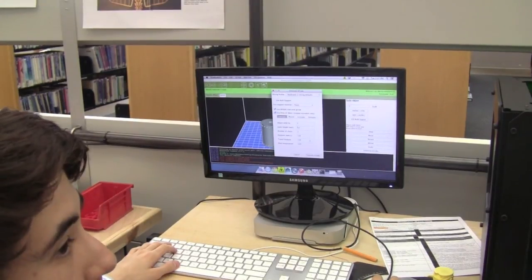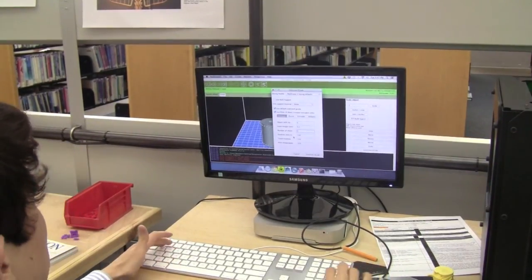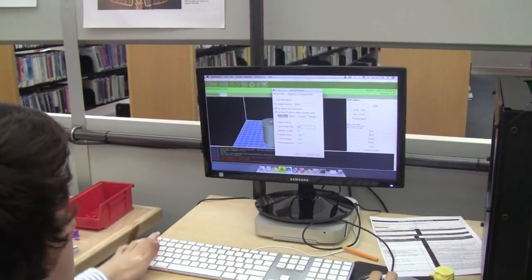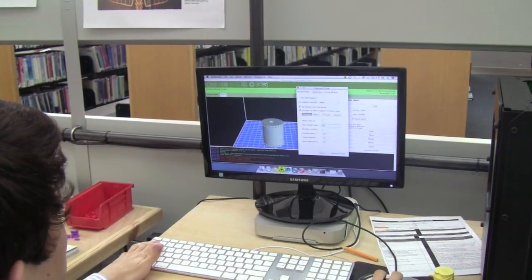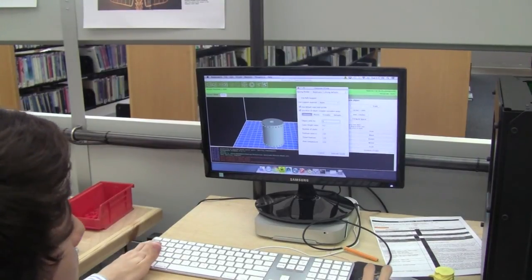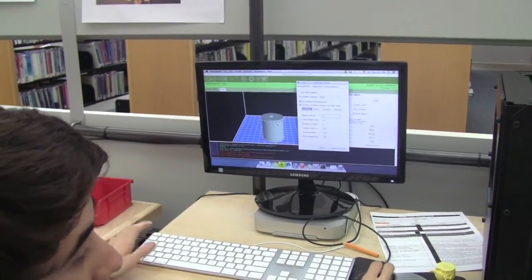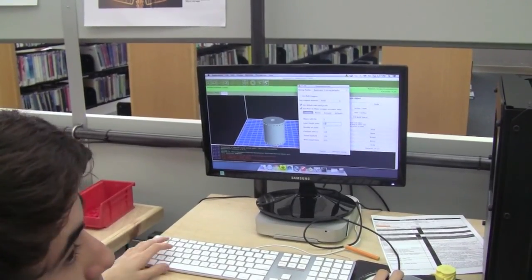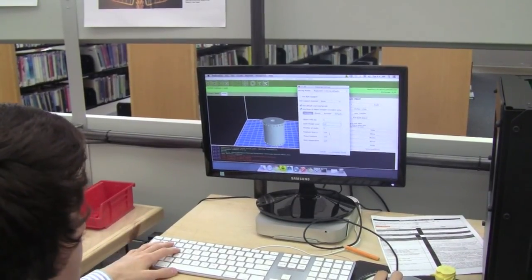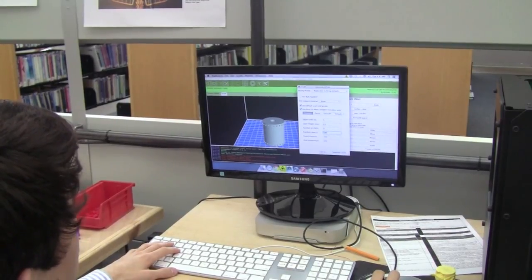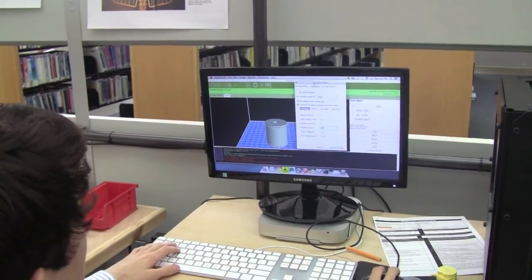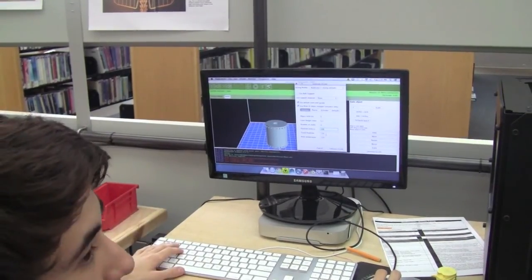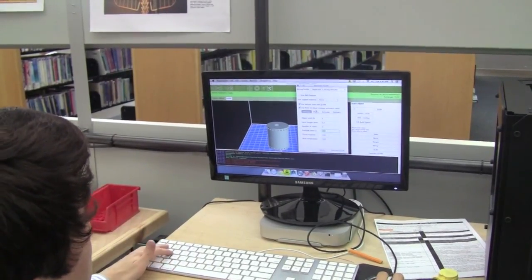So you say 0 shells. Oh yeah, I would do 0 for this. I just forgot to change it. I'm just demonstrating. Gotcha. For this print, 5% would make sense because it's a full cylinder. You wouldn't want that to be completely filled. Layer height, unless you want this to look really good, then you could do 0.1. Feed rate, it looks like it's supposed to mesh with something. I don't remember what this model is, but maybe we want to go slower, so it's a cleaner cylinder. It's a moving part. Right, maybe something like that. So those are the things you want to keep in mind.